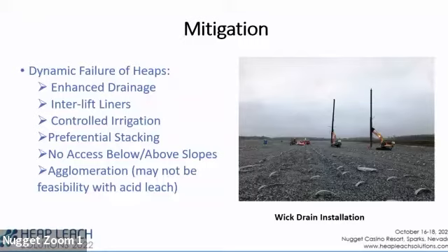Agglomeration for gold would fix this because the cement gives you cohesion, and cohesion isn't part of that equation I gave you earlier. So the full shear strength equation is effective confining pressure, so confining pressure minus pore pressure, times the tangent of the friction angle, plus cohesion with no correction for pore pressure. So the cohesion you get from the cement survives the pore pressure.